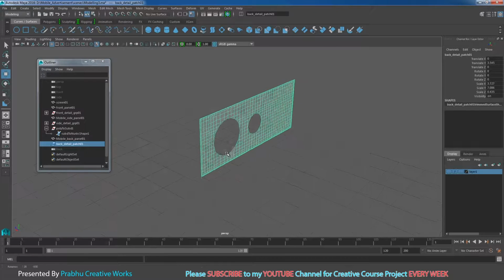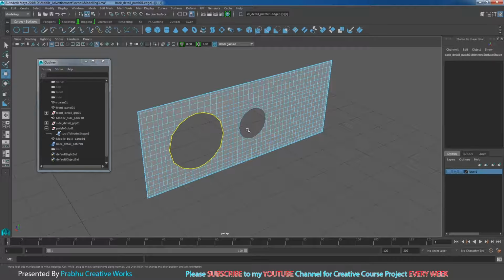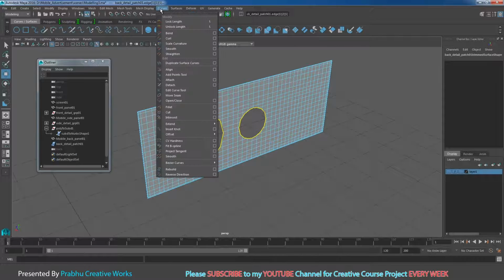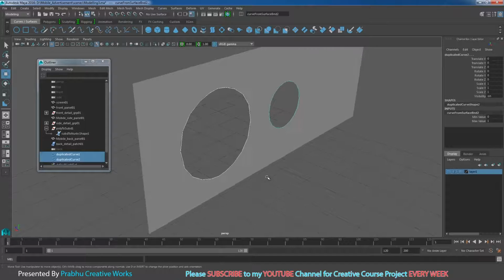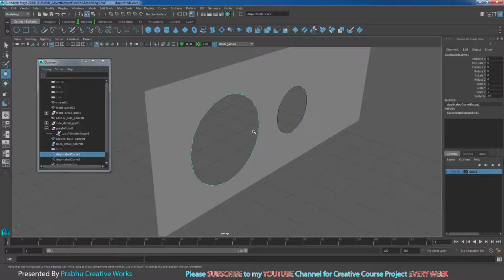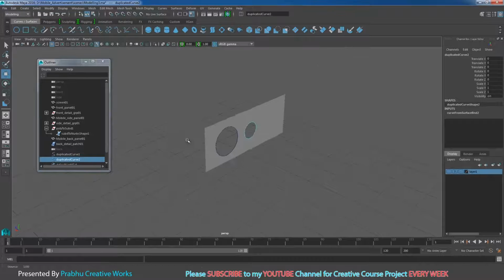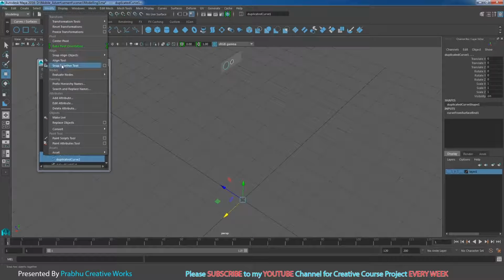Now right click and choose trim edge. Select this trim edge and shift select this trim edge, go to curves and choose duplicate surface curve, so that means you got a duplicated surface curve over here. Press W. See here our pivot is in the center of the grid, so I will select my two duplicated curves over here, go to modify and choose center pivot.